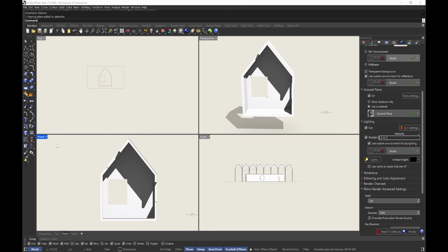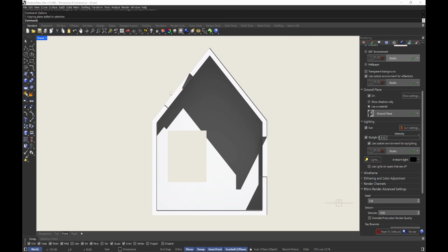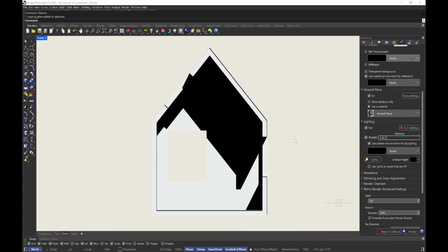And again, when you view capture a file, you want to make sure your Make2D and your view captured files are in the same place so that it makes the overlay much easier. You don't have to, but it's just much easier. One thing I'm not sure about, maybe my screen is just a little bit too high resolution, you see there's almost like a gradient over here. That's why sometimes if you do a stark black, it'll turn it off for you, which is good, and then you can change the opacity in Illustrator instead.